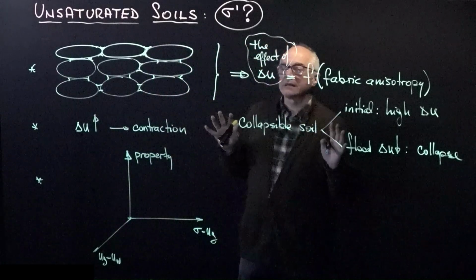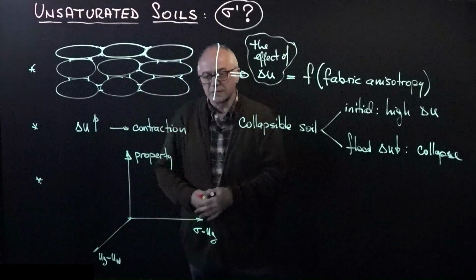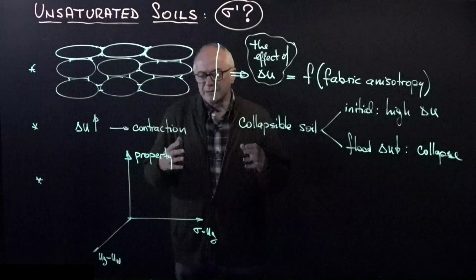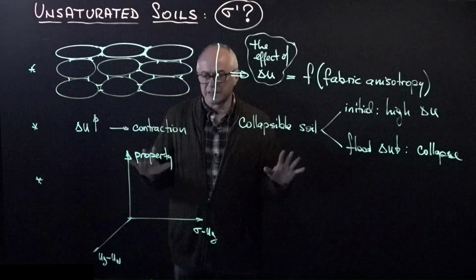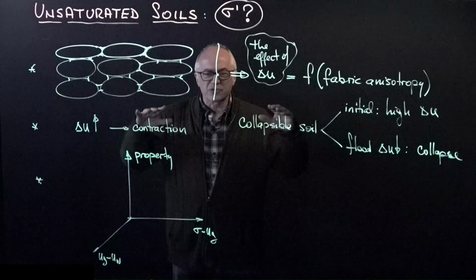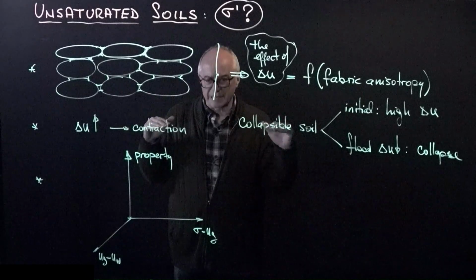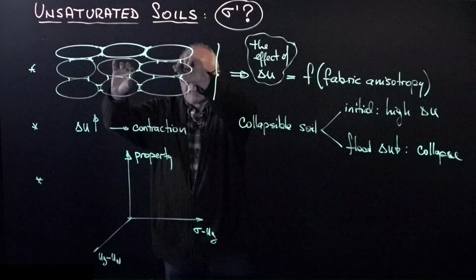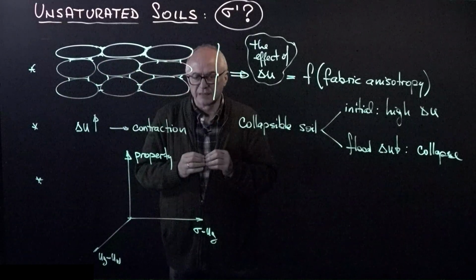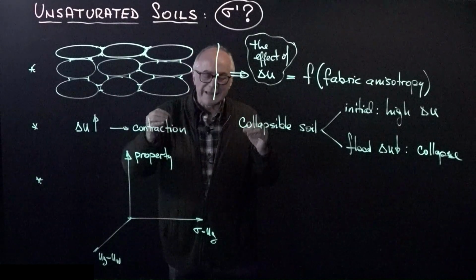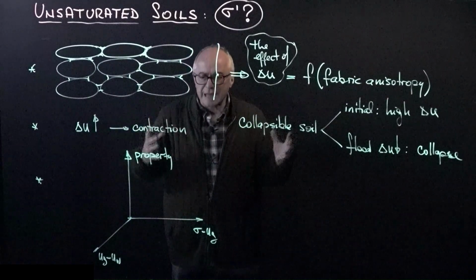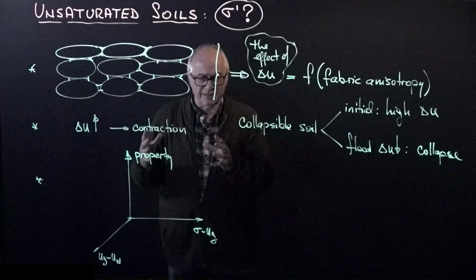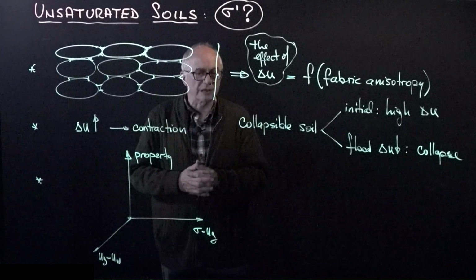And so you will find a large number of cases where the separation of the variables is the way to go. The multiple examples that I have presented here today, starting from a soil that is at the verge of becoming unsaturated until the water remains only in the pendular regime at contacts, begins to show the limitations of generalizing a formulation like the effect of suction on Terzaghi's effective stress initially proposed by Bishop.